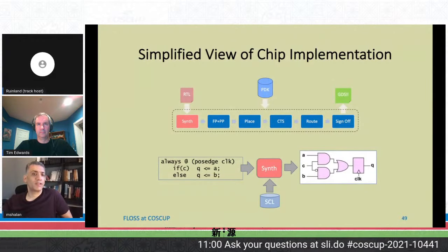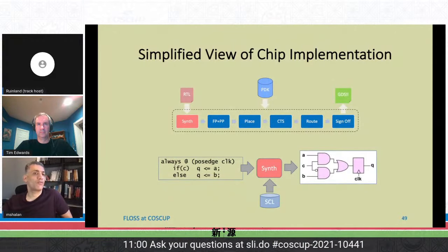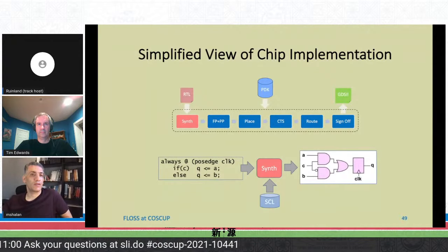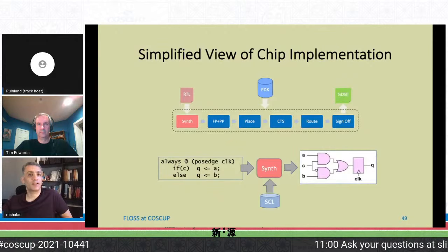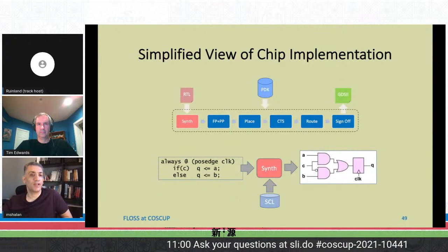So the gate level netlist just structures this description of the hardware by showing the components and how they are interconnected together. Verification activities using simulations and formal methods are also performed here in order to ensure that the translation is error-free. So using simulation and formal methods, we ensure that the gate level netlist performs basically the same function as the RTL that we started with.